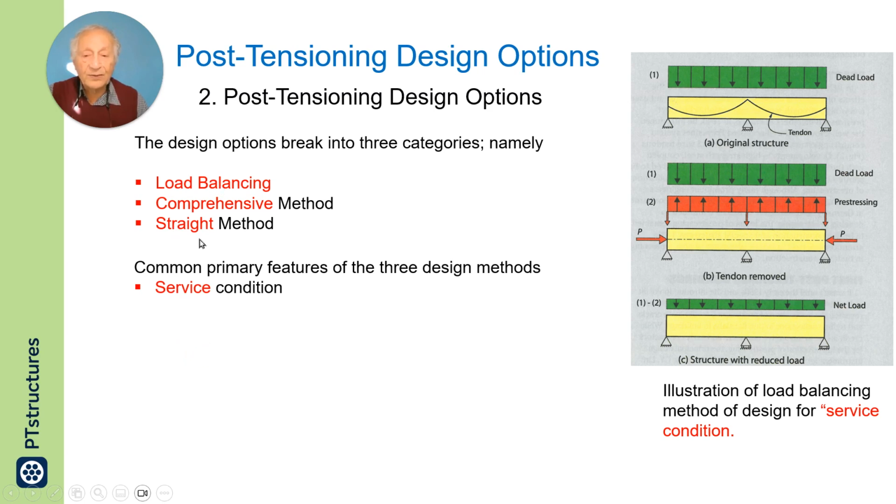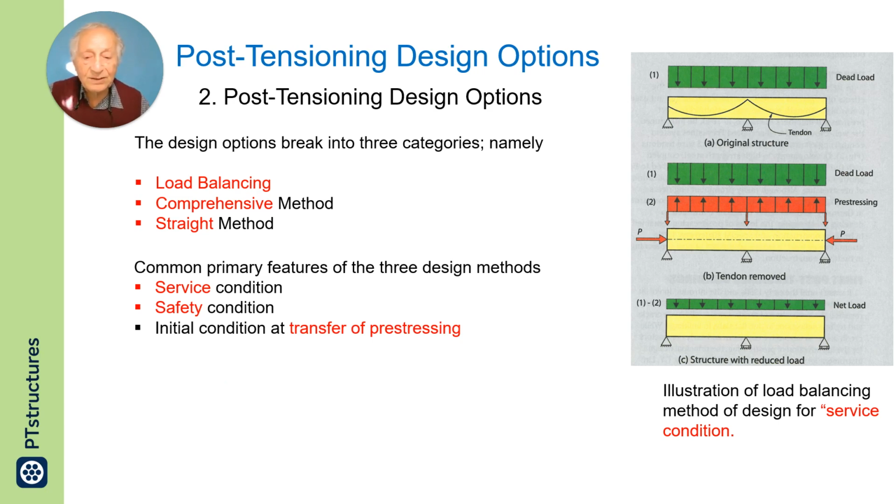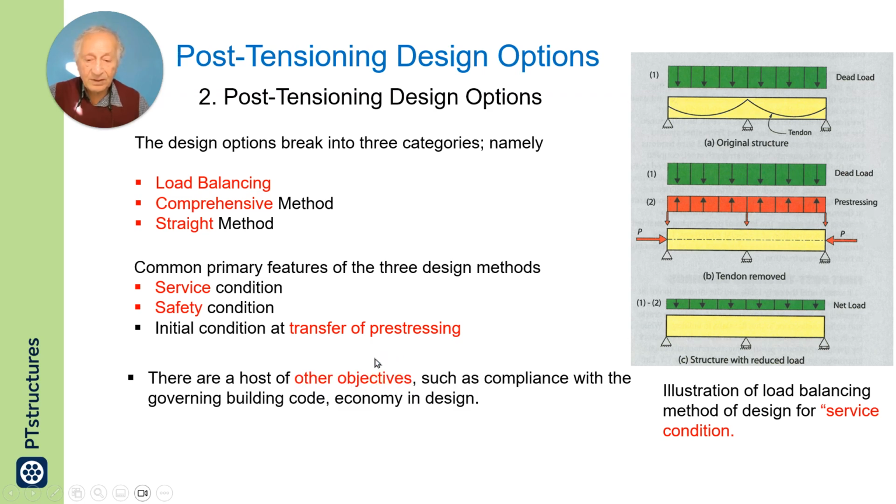Now these are the three methods. All three follow three steps. They have a service condition, which is deflection, cracking, vibration. They have a safety analysis section, which is safety against overload. And they also have a section on transfer of pre-stressing, that at jacking force there will not be rupture of post-tensioning.